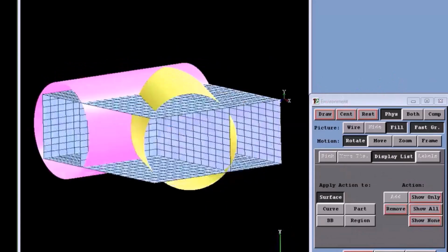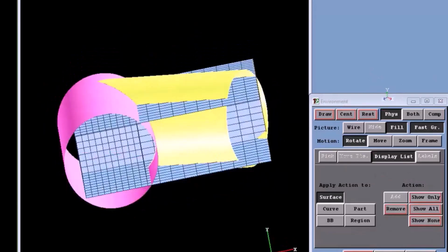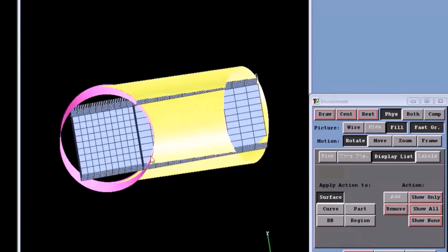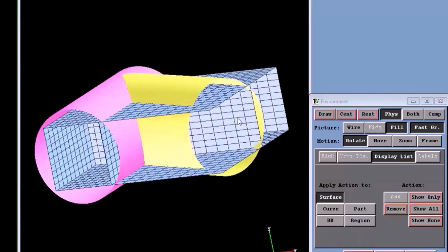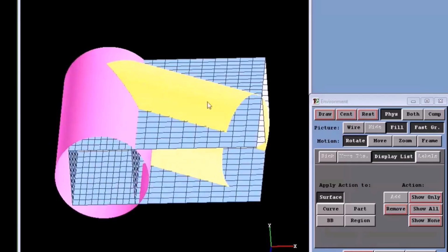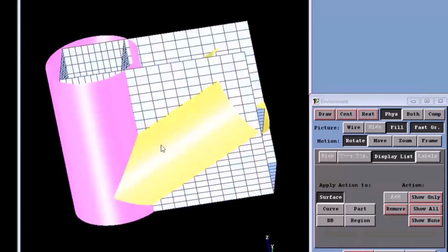Shells everywhere. So in the I direction, we have a face, a shell structure, for this part of the cylinder. We have a shell structure right here to cover this part of the cylinder. And we don't have a shell filling in this space right here, which corresponds to minus, minus, plus. Now in the J direction, we have a shell structure at the bottom and one at the top, so that we have shell elements that'll cover this, this, and the opposite faces down here.